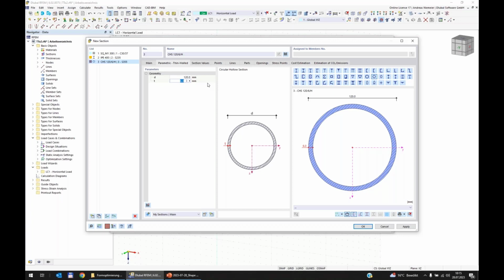So what I would do now is, I know we have 100 kilonewton on top and the length of the tower is 50 meters. So I expect a bending moment on the bottom of 1,500 kilonewton meters. And this 1,500 kilonewton meters, I believe, is really deciding for this structure. So we should find a cross section that can withstand or carry this load.